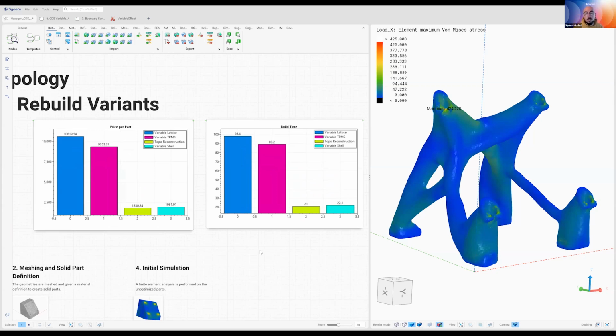And let's say I would like to add one small thing, Andrew. When we are doing this analysis for pricing and feasibility, behind the scenes we also do the orientation, finding the right orientation to print, doing the right nesting to print, and based on that, we also estimate what the support structures are, what the volume of the support structures will be, and based on that, the pricing comes out. So it's not a volume-based pricing. It's a much more in-depth analysis of detailed pricing based on the orientation.